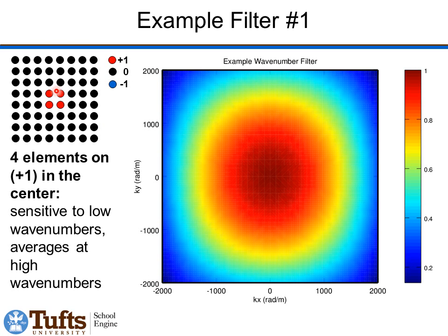So here's some examples. Let's say I just put 4 microphones here and turn them all on and turn everything else off. I'll get a wave number filter that looks like this. So it has a high output for small wave numbers, close to 0, where 0, 0 is in the middle. As long as the wavelengths are long, then we just get our one output. But as the wavelengths get shorter and shorter, so the wave numbers get higher, at some point you get fluctuation across this aperture, and then the signals cancel out and your sensitivity drops.